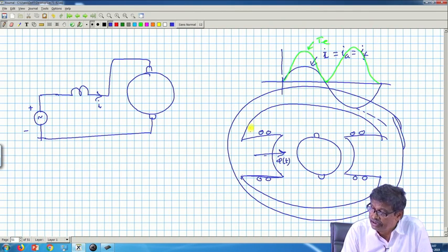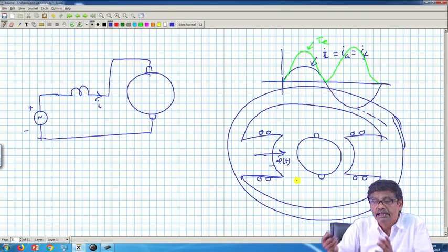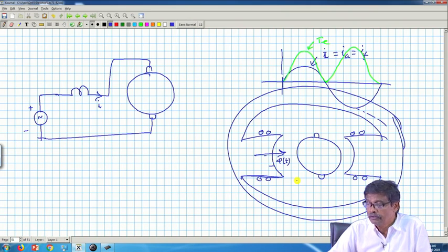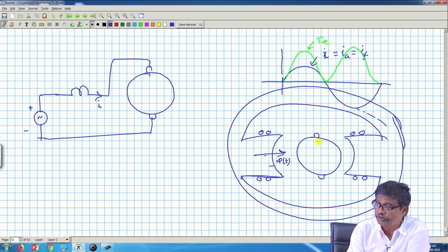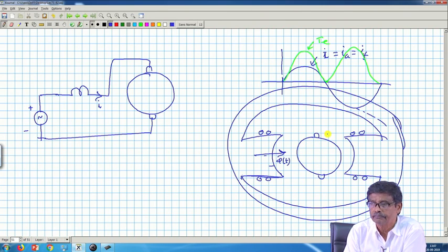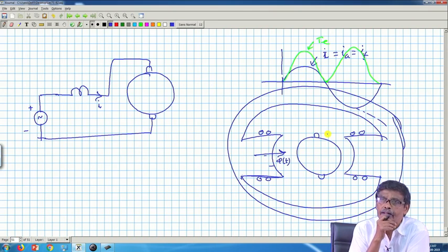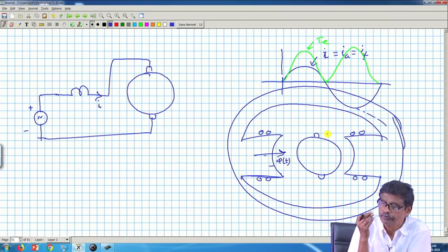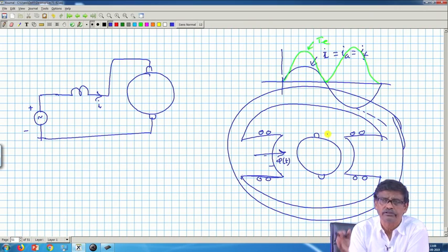Therefore, this flux will flow through the yokes, and if it is solid iron, eddy current loss and hysteresis loss will take place in the stator iron structure as well. In the armature, in any case, even in DC operation, eddy current loss and hysteresis loss take place, and that is why the armature is laminated in a normal DC machine as well. Remember this fact: for a DC motor which is to be operated from DC supply alone, if you insist on that, then use solid iron for the stator iron structure, no problem. Of course, the armature is to be laminated.